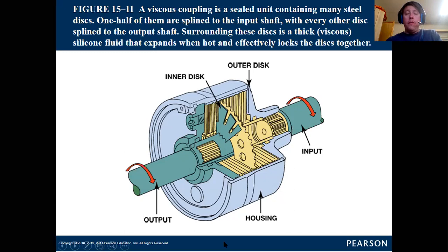This component right here is a viscous clutch. Now, manufacturers go about this several ways on your lighter duty vehicles. Lighter duty meaning like your little Toyota RAV4, right? Your pickup truck, Toyota Tacoma. I don't know about the Toyota Tacoma. That's an actual transfer case. But your little SUVs, your sport utility crossover things, your all-wheel drive cars that are four-door sedans that they say all-wheel drive. They're not actually all-wheel drive.